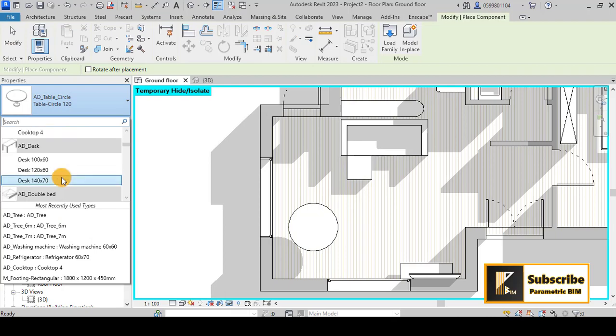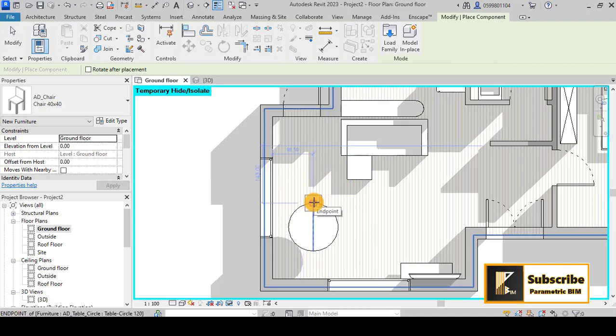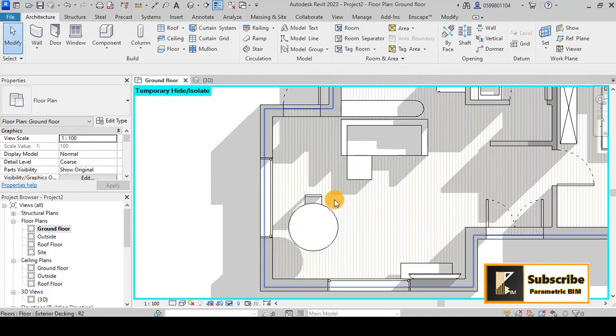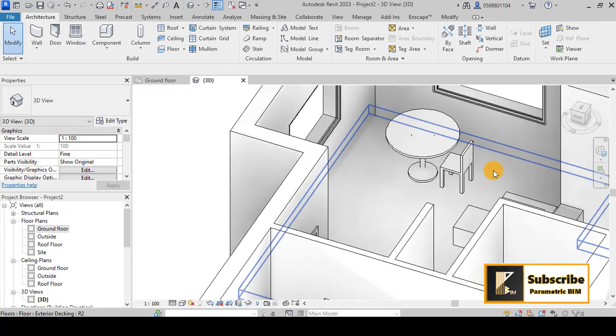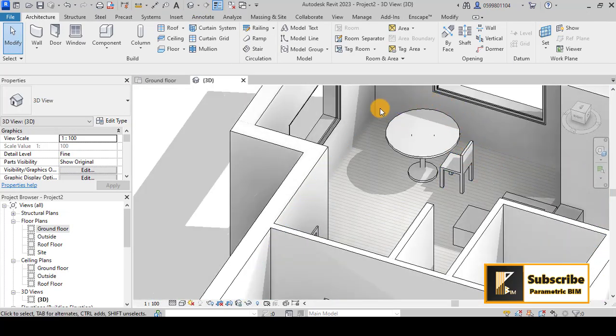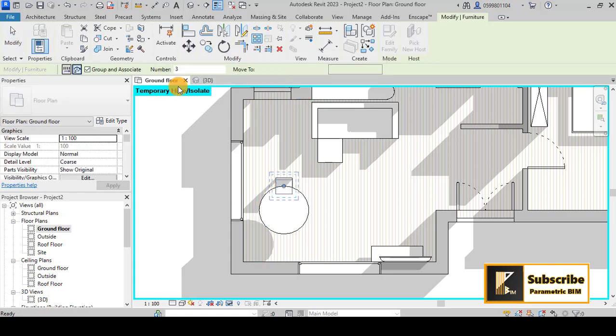I will choose a chair, for example this one. Space to rotate it in the same. And as you see, I have here one chair with this table, but I want to make 4 chairs around this table. So simply you can copy it maybe and rotate, but instead of doing that, you can do the array and choose the polar.